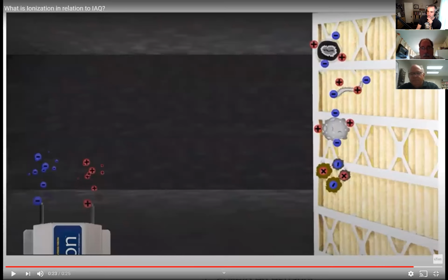And then lastly here, obviously we talked a lot about PCO. So at the core, you have to have UVC bulbs. So at the core, you're always going to have UVGI in the application. But if you're adding in an airstream product that uses PCO, then you could say, great, I'm installing UVGI technology in the airstream plus adding PCO, aka photocatalytic oxidation. Because without the UVC wavelength bulb in the UVGI technology, you can't create the PCO. That is a required component. And again, with some of our commercial stuff, you can add that on.